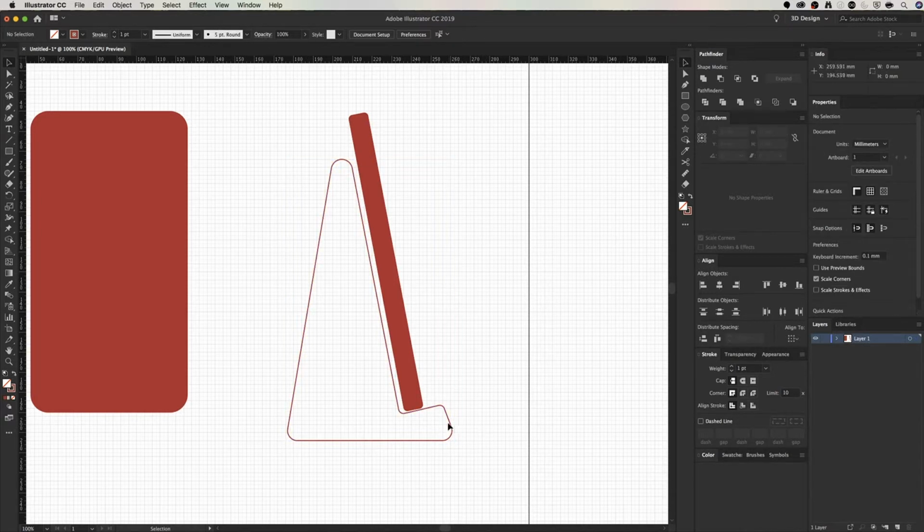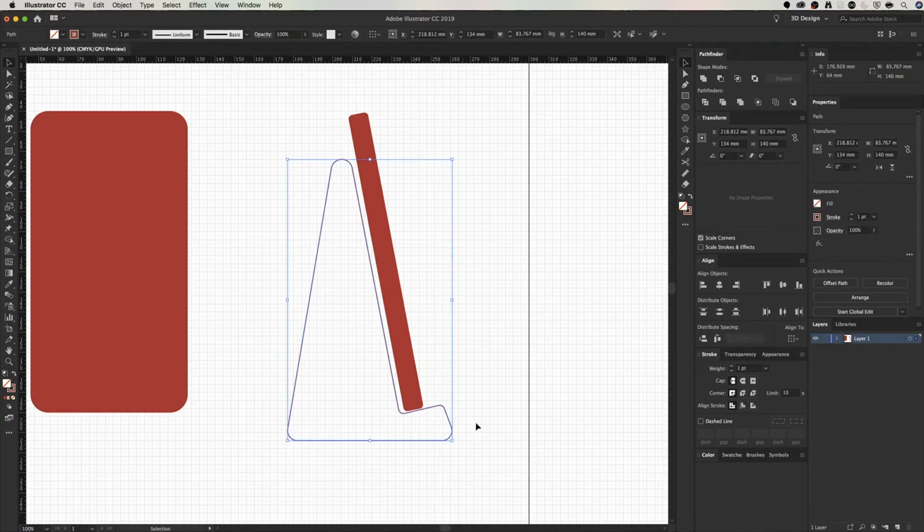that allows me to do really rapid design things. And so this is really good because often in designing for 3D printing or designing to create anything to fit into anything else, you're often doing a lot of offsets, and the offset path is a great way to do offsets, obviously, for things to sort of fit together, to have your tolerances set correctly. So it really allows you to finesse those tolerances in a really precise way.